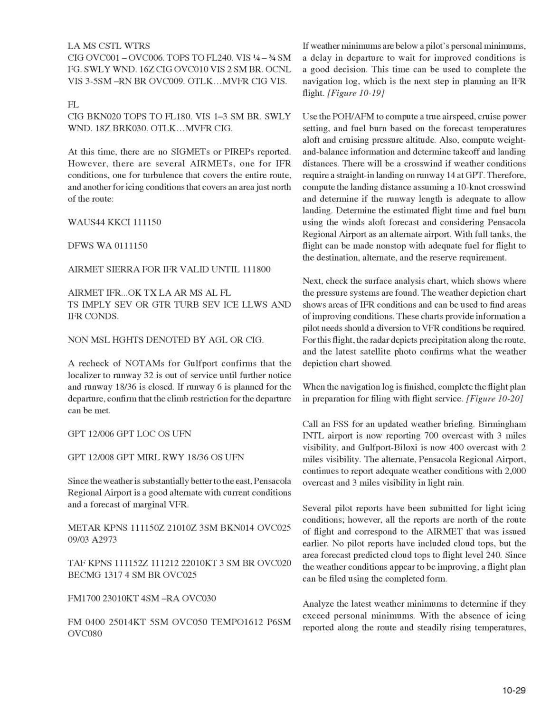Several pilot reports have been submitted for light icing conditions, however, all the reports are north of the route of flight and correspond to the AIRMET that was issued earlier. No pilot reports have included cloud tops, but the area forecast predicted cloud tops to flight level 240. Since the weather conditions appear to be improving, a flight plan can be filed using the completed form.